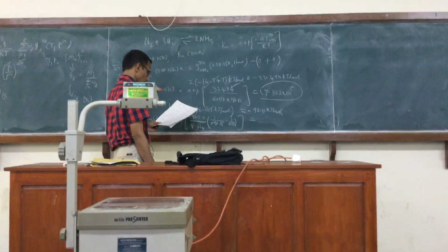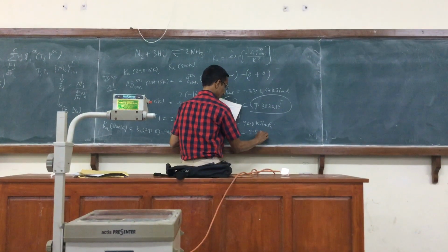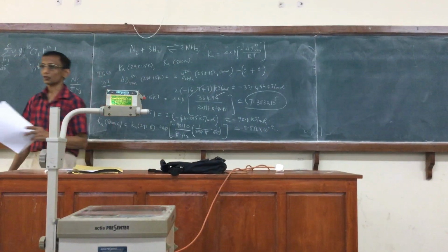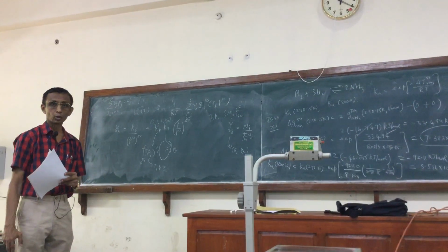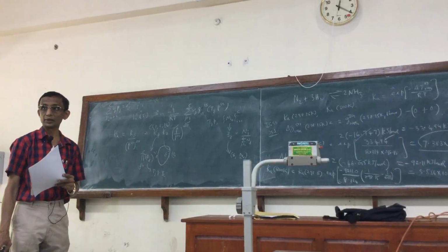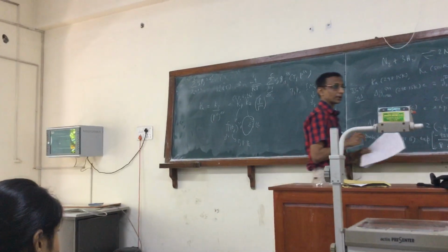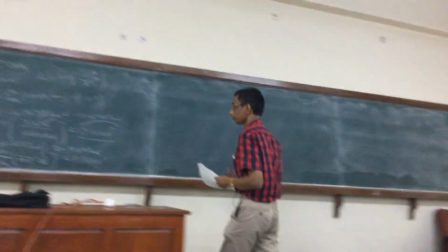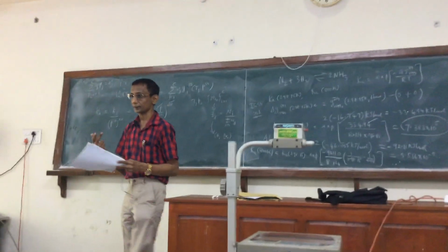It is very low. It is 5.556 times 10 power minus 5. You can see it is almost 10 orders of magnitude lower because of the exothermicity of the reaction. This is always a trade-off for exothermic reactions, because the equilibrium conversion will decrease with increase in temperature. As you can see, the equilibrium constant is decreasing.